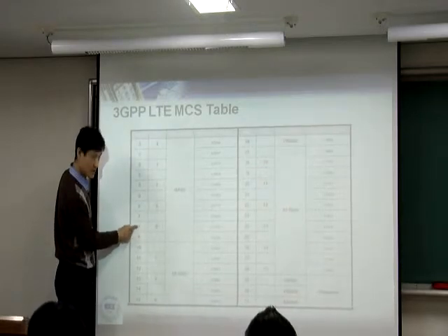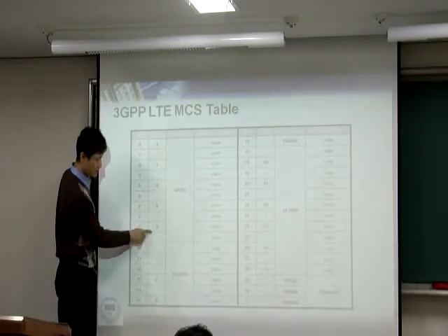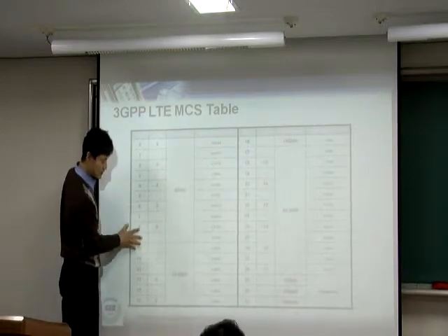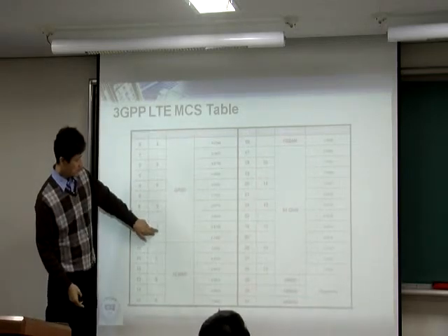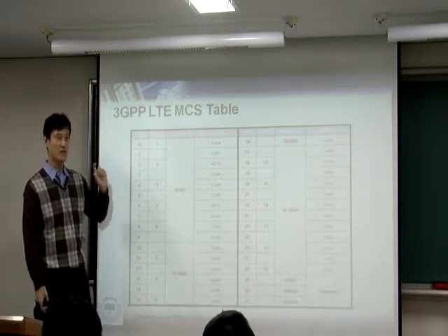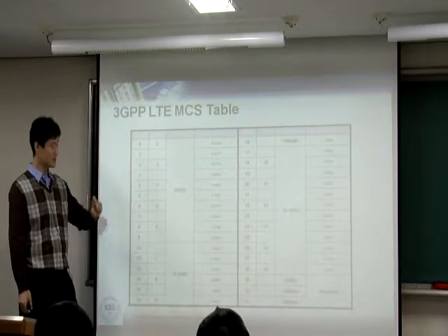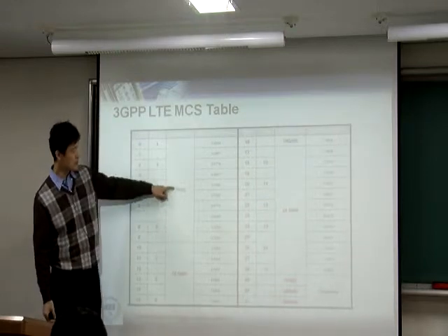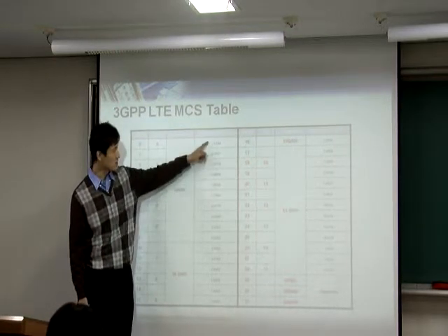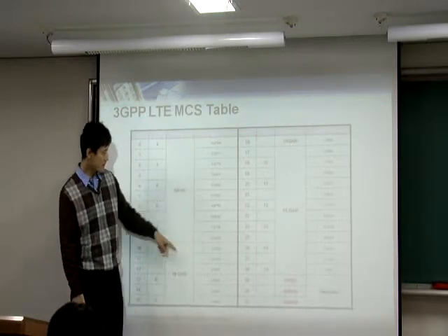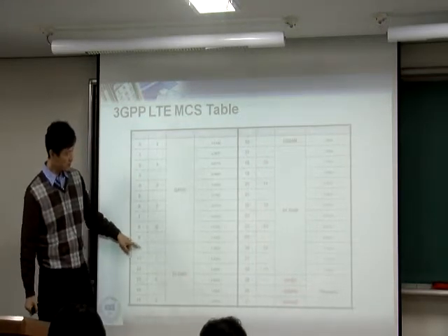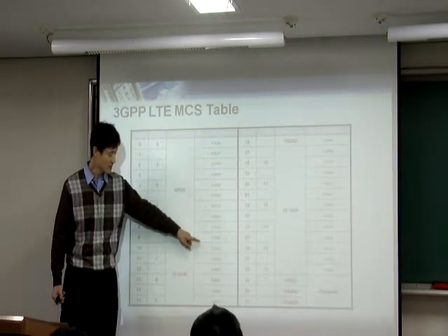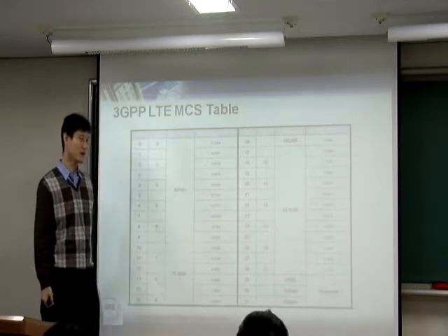The difference between these 3 MCSs is that these 3 are mapped to the same CQI 6, which is very interesting, because when we receive CQI 6, it means that you have the same SNR somehow, right? But there are three choices you have. The first two choices use QPSK, but with a different spectral efficiency. But the third type uses 16 QAM, not QPSK, but you see the same coding rate. How does that happen?